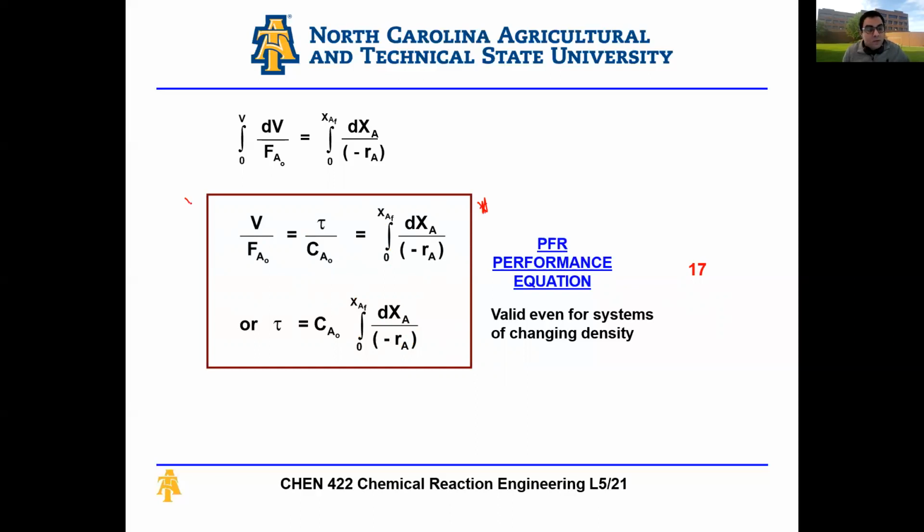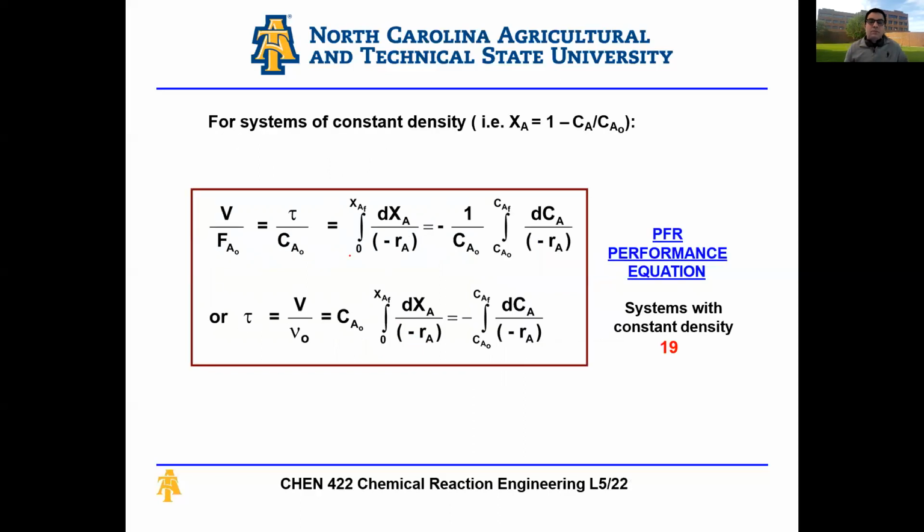And this is the third important takeaway from this lecture, right? You need to know your performance equations. You need to recognize how to use them. And for all three of them, the way to use them is through this, minus RA. Find out your reaction rate equation, plug it in here, and it becomes a math problem. Just move things around, algebra, find the right equation, maybe convert from FA0 to CA0, whatever it is, solve your problem. All right.